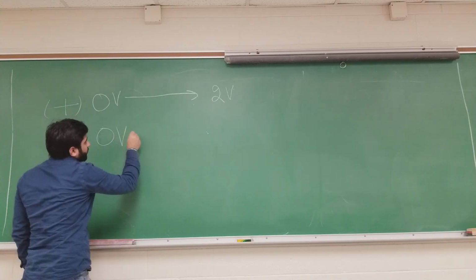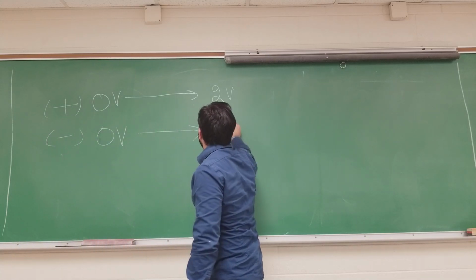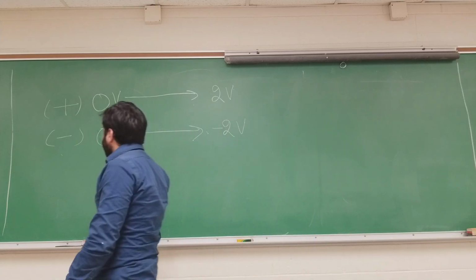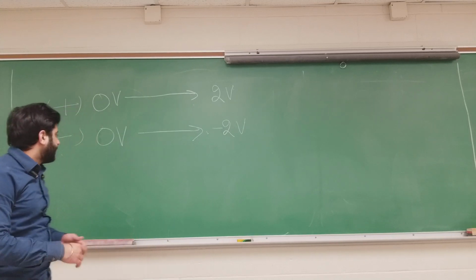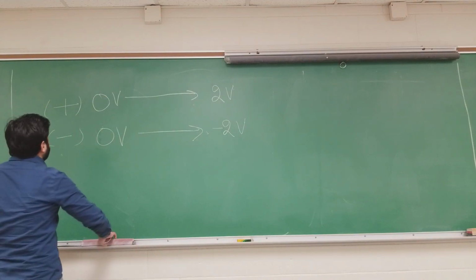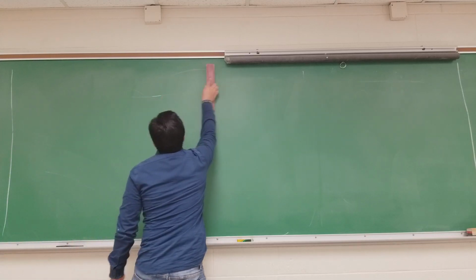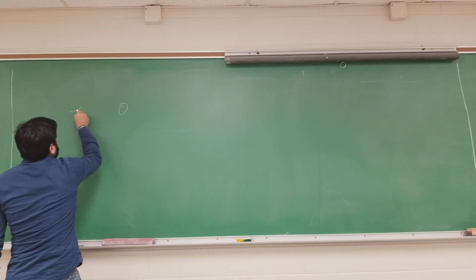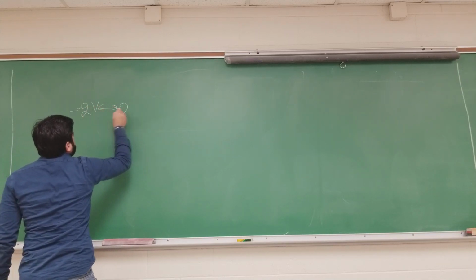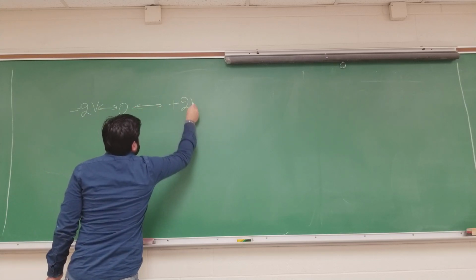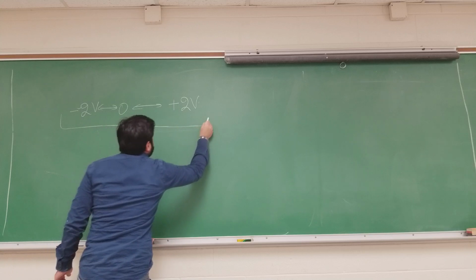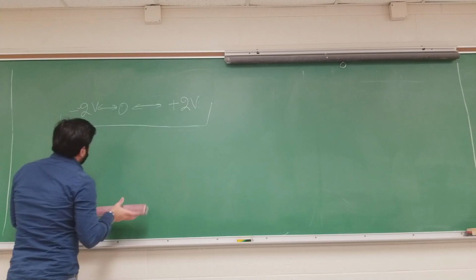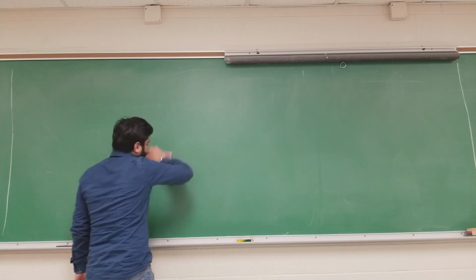Going from 0 volts to some XYZ value, it could not be -2, it could be something else, but we will have a deadband. That's a region in which there will be no rotation. So for our experimental purposes, we are interested in finding the region in which the motor does not rotate, and that will be regarded as the deadband.